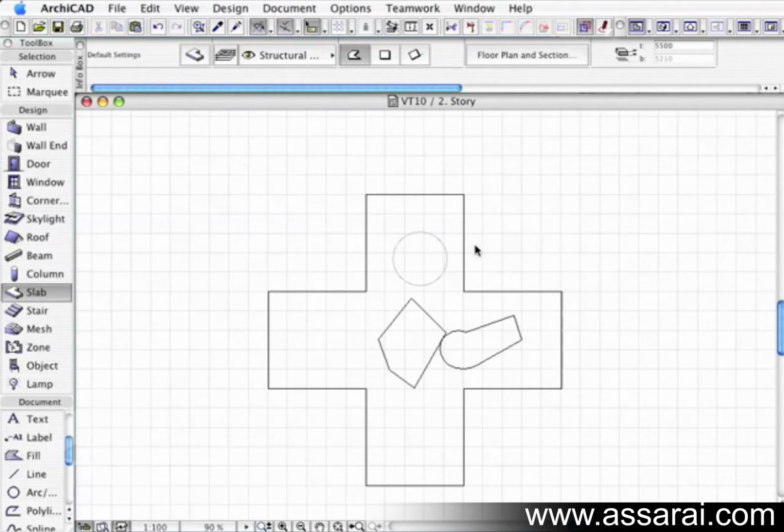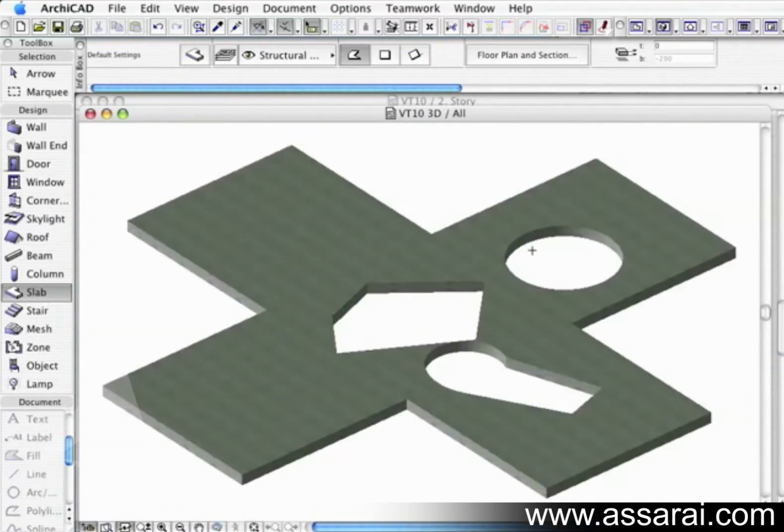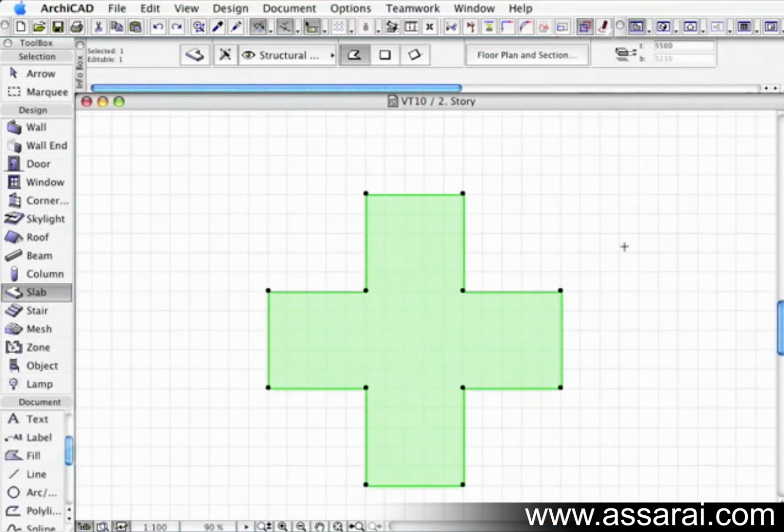Then if I click to the slab tool, hold the shift key, select the slab tool, then I'm going to hold my spacebar down, and as I hold the spacebar down, we'll notice that the cursor will change form so it looks like a magic wand. And the magic wand's got all lovely little sparklies around it, but as you go over the 2D line, it changes into a polygon type shape. While I'm still holding the spacebar down, I left mouse click, and it will cut a hole that copies that circle that we've actually drawn. So if I deselect it and go to the 3D window, we can see that we've actually created a perfect circle in there. So I'm just going to close it off now and go Control or Apple Z and undo all those.